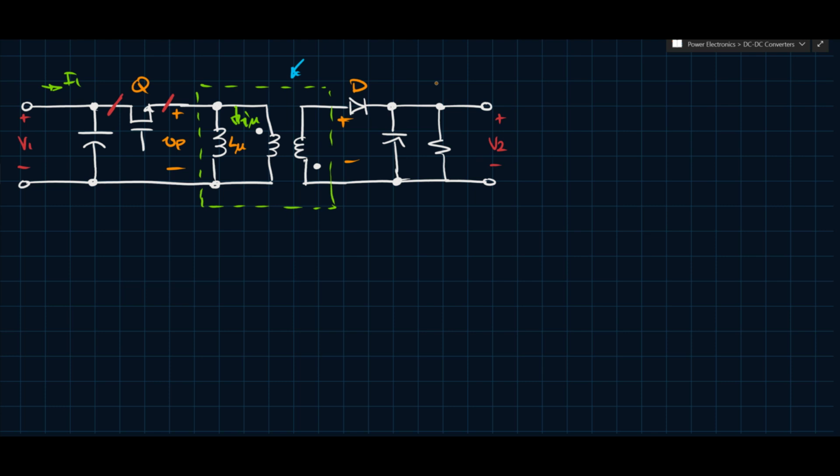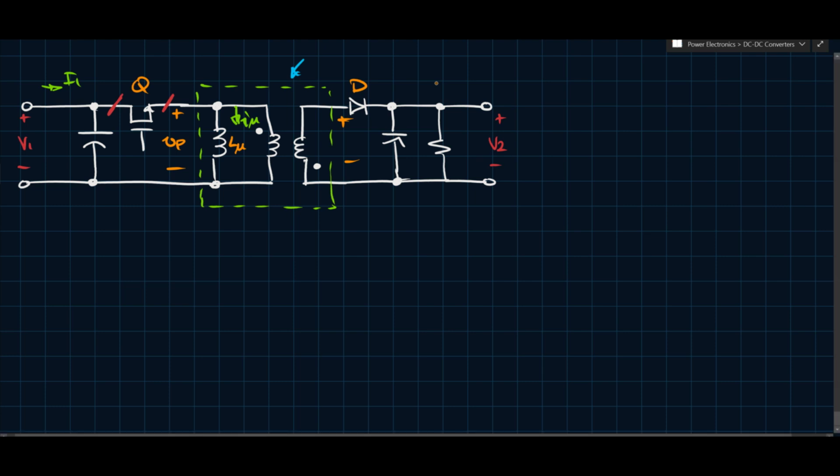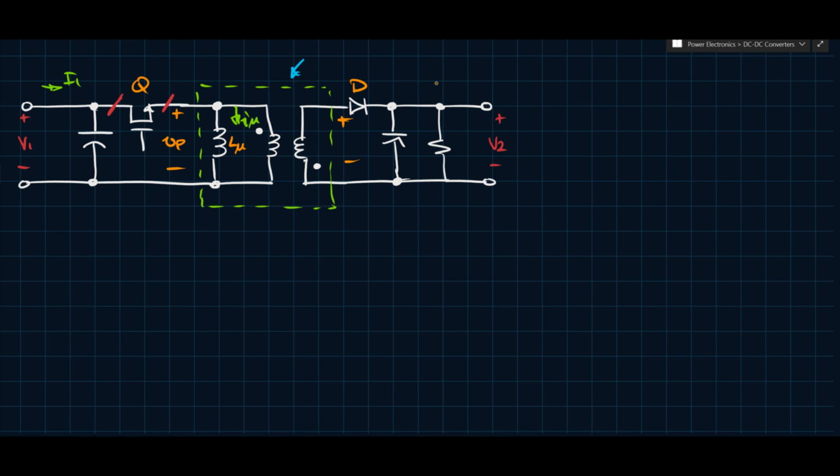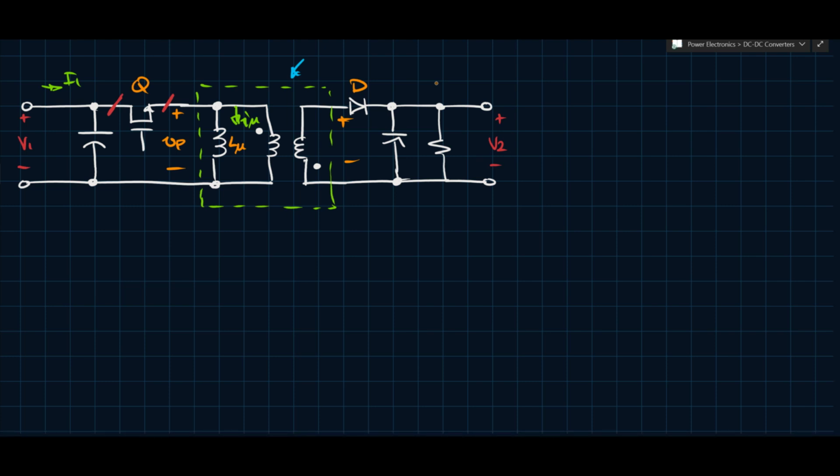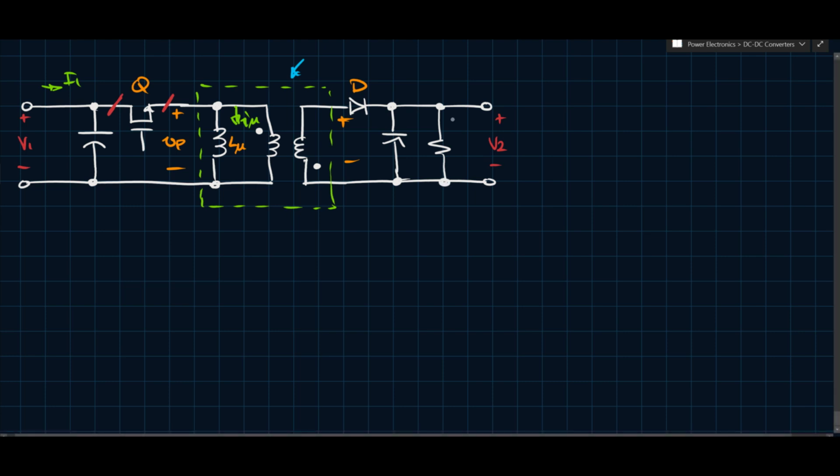The spot on the screen that would develop as a result of the picture being projected there would fly back, so to speak, to form a new line every time a new line was required. For that reason, they call it the flyback converter. You can also call it the isolated buck boost. Essentially, that's exactly what it is.